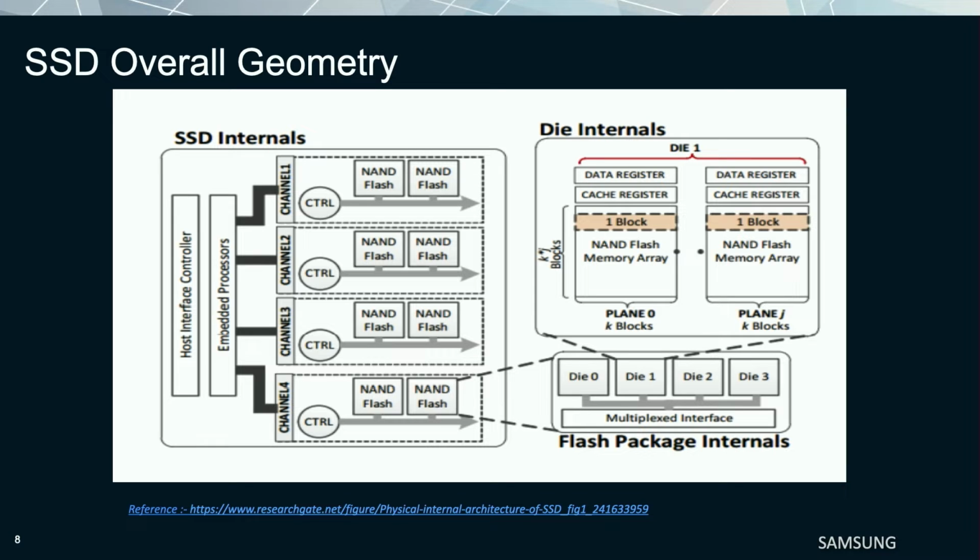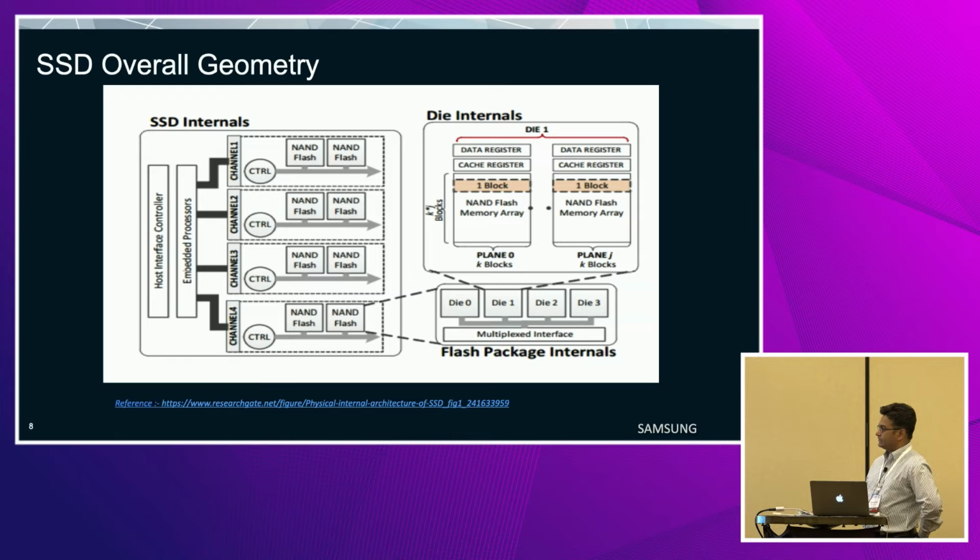Coming to SSD architecture, this is the overall picture of the SSD geometry. As I said, parallelism and interleaving are the two key features of SSD. If you see the host interface, there is an embedded processor with the device head, and hardware channels to achieve parallelism. These NAND flashes are arrays of flashes where each channel operates.